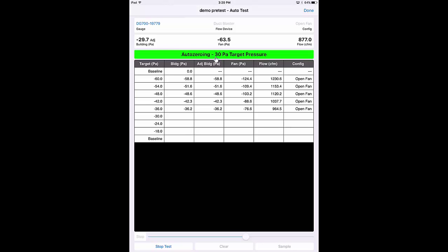It will also calculate the accuracy of the test, the accuracy repeatability, and a correlation coefficient, and we'll show that when we look at the results. We'll want that correlation coefficient to be above 0.99. On windy days, that can be an issue. If it's less than 0.99, you'll want to run another test to try to get some better data. And it calculates the accuracy of the test. So based on all of these different data points, you'll get a lot of good data.